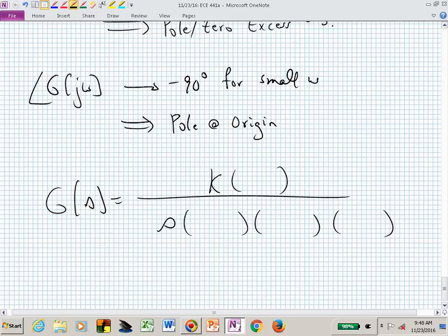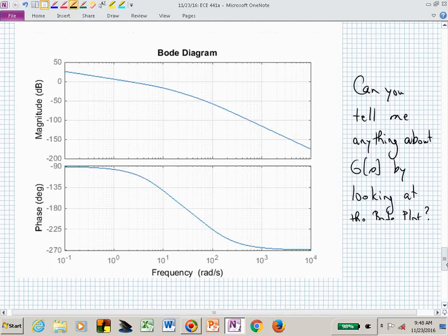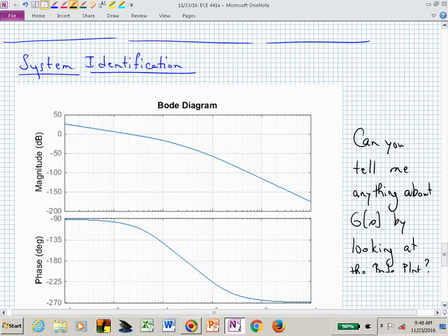That's what I've now determined from just looking at the phase curves extremes. Can I go back and find any of these frequencies? Do I ever seem to go up in slope in my magnitude? So I probably don't have any 0 factors, do I?